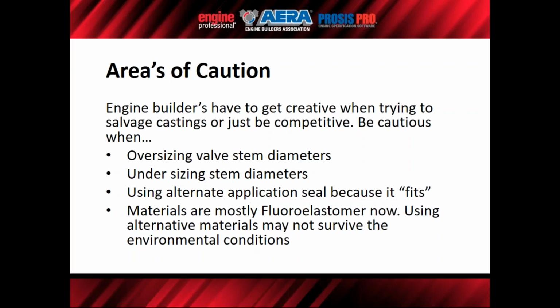The use of alternate application seals, because it fits. Been there, done that, been successful, been unsuccessful. Just because this seal fits an 8mm stem, well, I'm going to stick it in this application, it should work just fine.